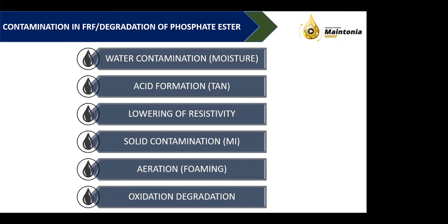Then zinc plated filter elements added additional zinc to the oil, which caused a lot of foaming. Then the mild steel parts and pipelines used in the machine created havoc in the oil. And the ultimate result was replacement of the oil, flushing of the system, and topping up with new oil.